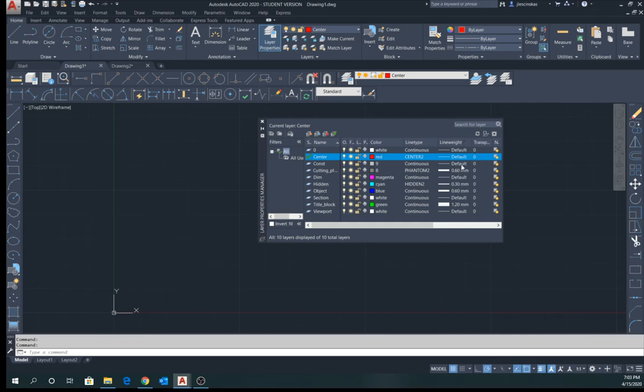The other thing that we're doing here in this drawing is we're beginning to add line weights. So we're changing some of the line weights from the default setting to a different setting. As you see in the book, there are 4 line weights that are being changed. So you can go ahead and change those line weights as well. So change these colors, set up the proper layer names, set up the line types, and then set up the line weights. You can go ahead and pause this video and then continue on when you're done.